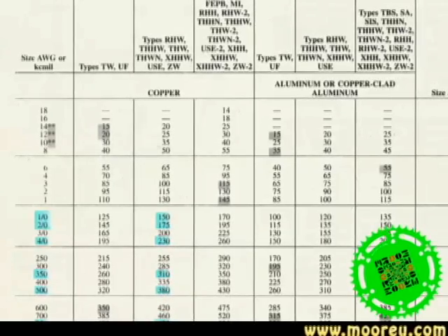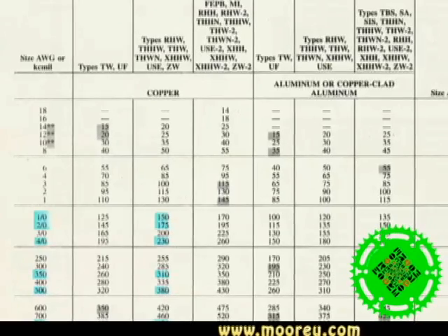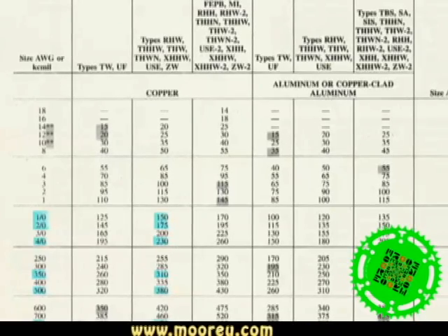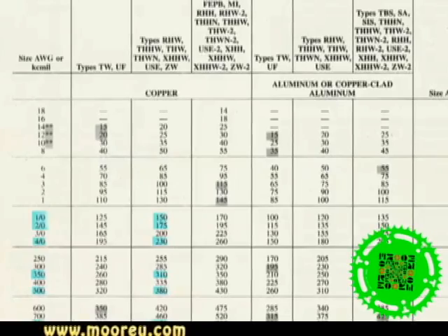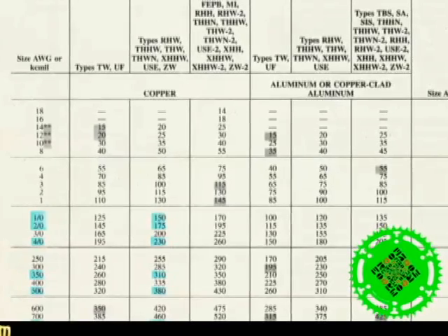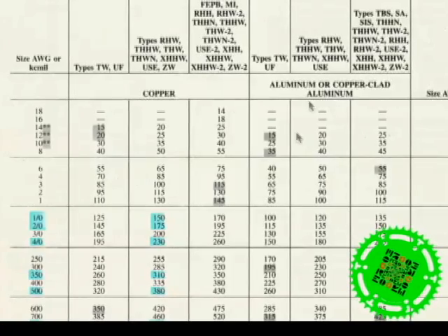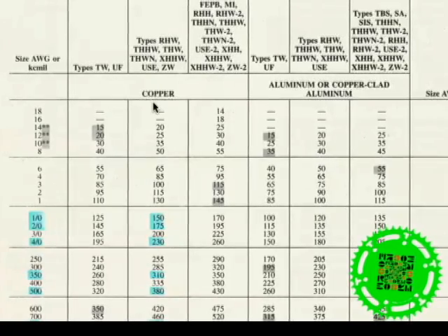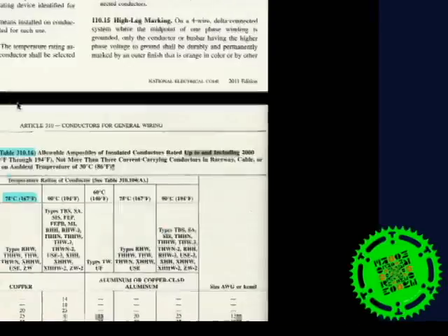So these will be the values that each one run of wire can carry. So for example, a 750 MCM cable, one run can carry a maximum of 475 amps. And everything that we will be sizing for this application is in copper only.